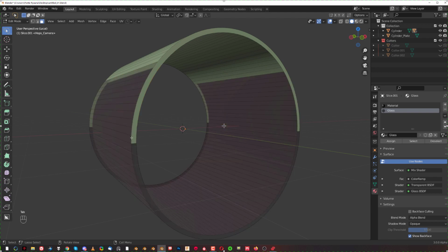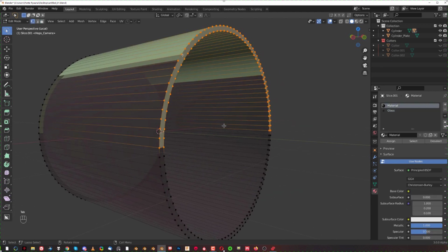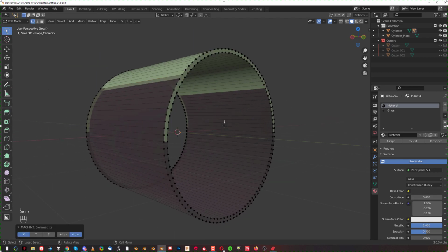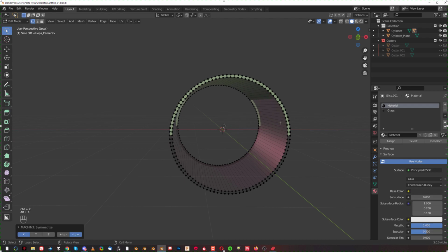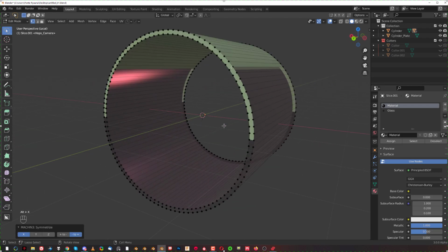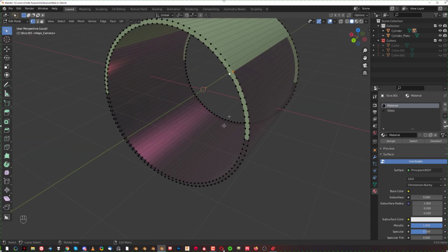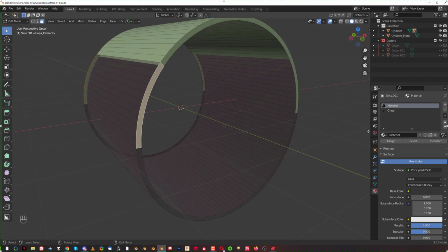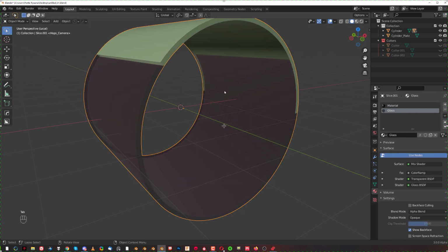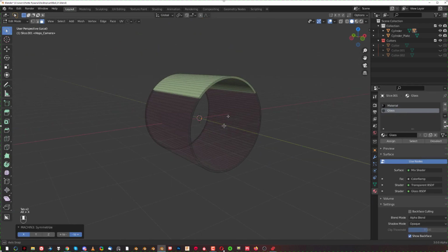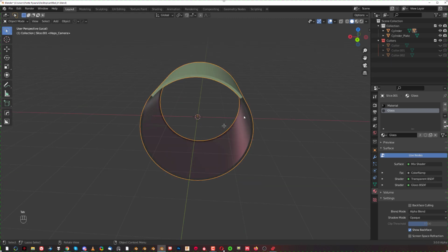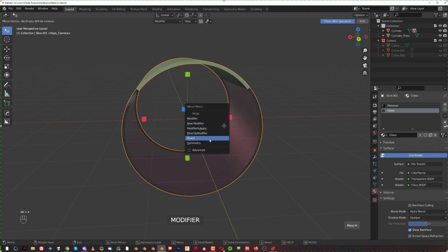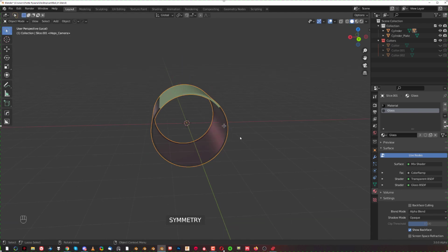Now we got some mud in here, which is kind of weird. So what we're gonna do is we're gonna connect these two here with J, and we're gonna copy this to the other side, so like this. And we're gonna do the same thing in here, so connect these two with J, and we're gonna select these two bits, okay, because we need glass in here, and we're going to assign glass, and Alt X with Mesh Machine to the other side. If you don't have Mesh Machine, what you can do is go to solid view, Alt X, D with HardOPS, symmetry, and the same thing, right?